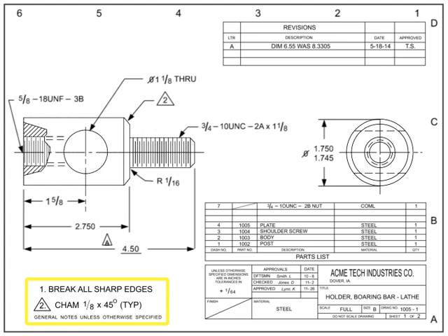General notes apply to the entire drawing. Tolerances, general handling or material specs, color specifications, testing requirements, or packaging instructions are examples of general notes. Flag notes are notes that apply only where the flag appears in other areas of the drawing, such as the field or parts list. Typically, the callout includes a flag icon. Some drawing standards call these types of notes delta notes, as the note is indicated by a triangle in lieu of a flag. Flag notes can be annotated by either alpha or numeric characters.